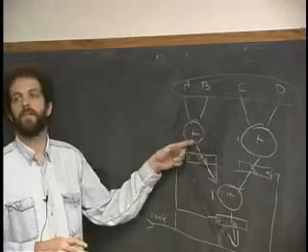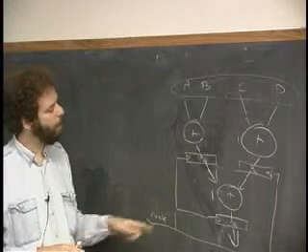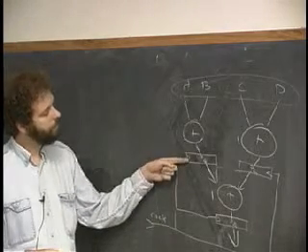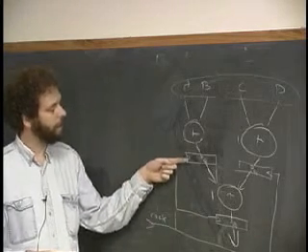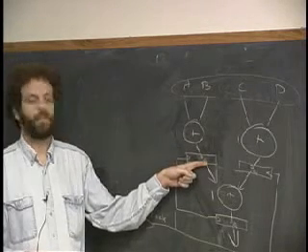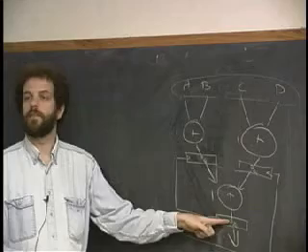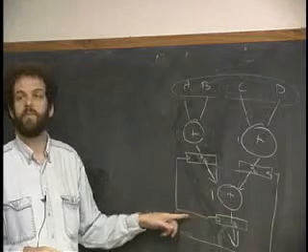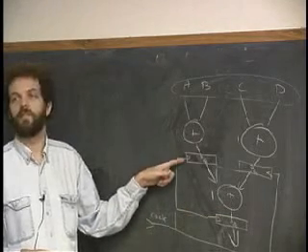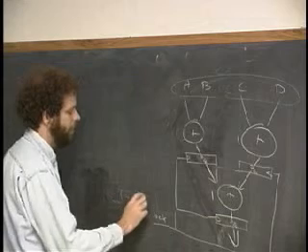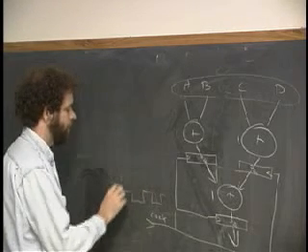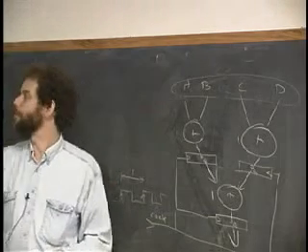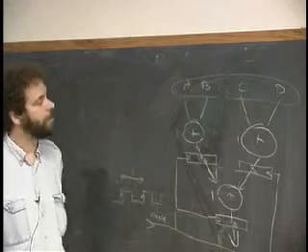All of the slow stuff happens in these adders here. So how often can I clock this circuit? Well, period of 1, right? Every time I clock this, let's say it takes very little time for the Q to come out here. The propagation delay to get to D here, oh, and I'm also going to say the setup time is very small. Okay? I can clock this thing 1 unit of time after I clock this one here, which is to say that I can put in a clock over here which has a period of 1 unit of time. Like that.